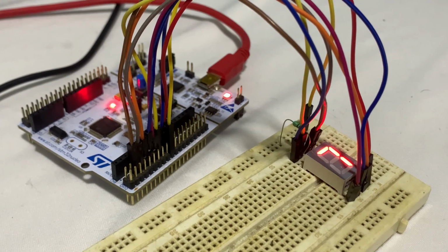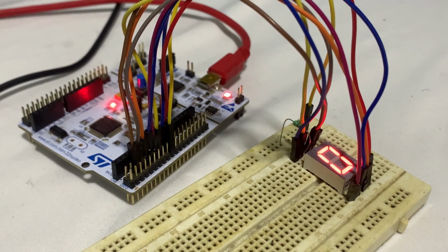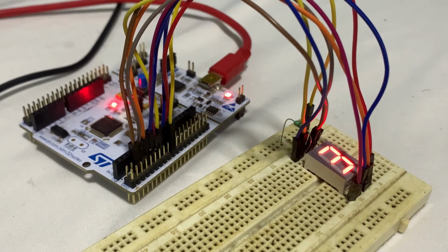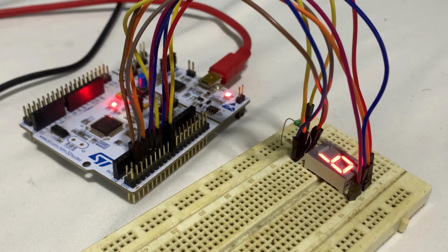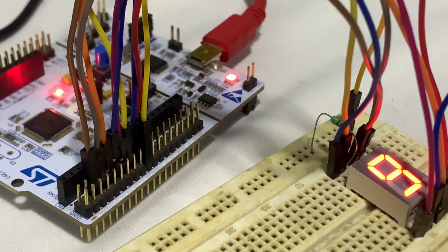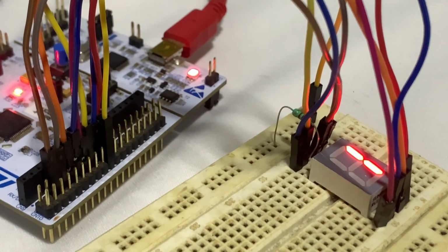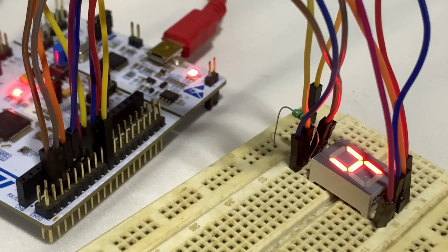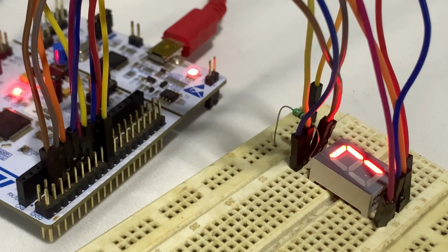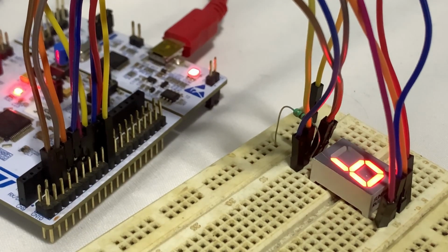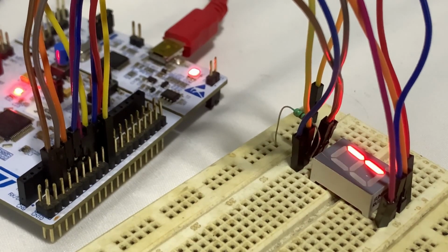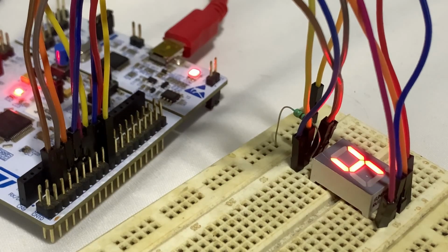Now you can see this is the output which I got in my hardware after building this circuit on the breadboard. The display, that is the common cathode 7 segment display, is displaying numbers from 0 to 9 at a time interval of 1 second for each number, and when it goes beyond 9, again the number rolls over to 0 and the process continues. So the program is working fine as per the logic that we have written.